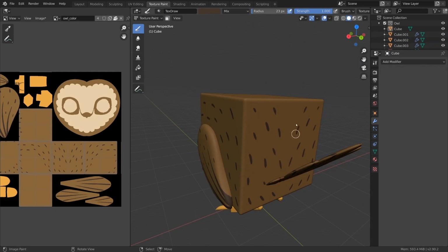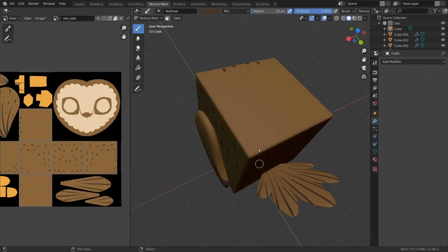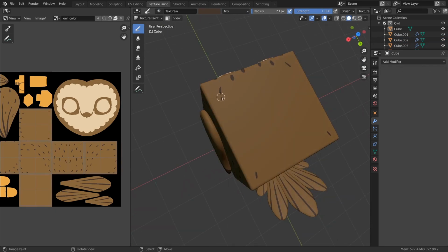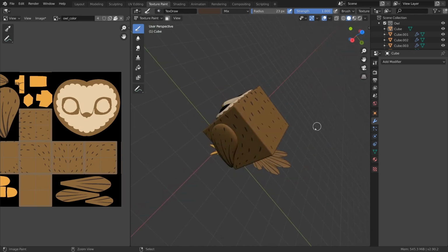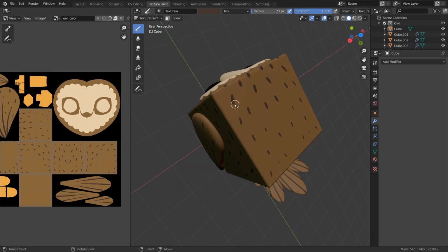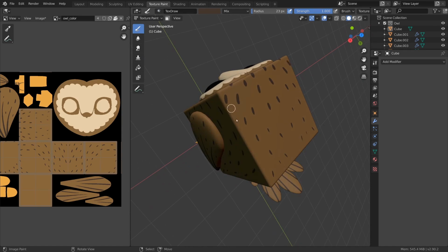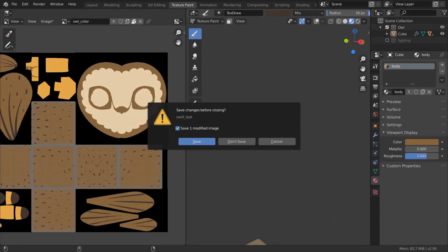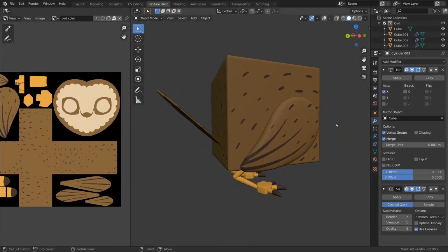As long as you're just painting on a single texture per material, you should be good to just paint in the usual solid workbench shading. While painting, or once you're done, don't forget to save the painted texture as a separate file, or even pack it directly into the blend file itself, and save it regularly. If you should try to close Blender, it will even ask you to save the texture, so no progress is lost.